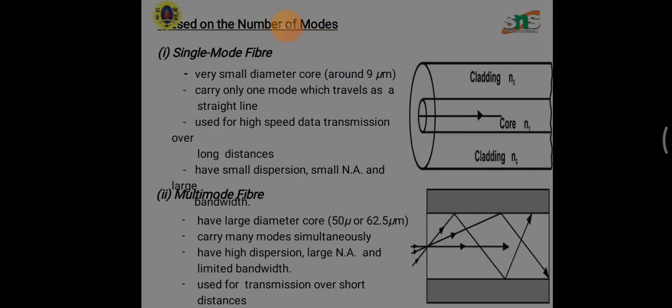In general, single mode fibers are step index fibers. These types of fibers are made from doped silica. It has a very small core diameter so that it can allow only one mode of propagation, and hence is called a single mode fiber. The cladding diameter must be very large compared to the core diameter. Thus in the case of single mode fiber, the optical losses are very much reduced.